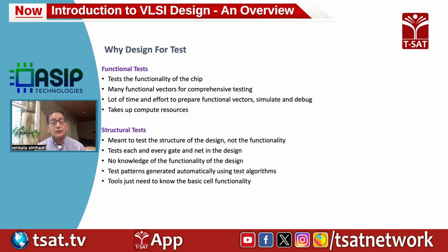There are two ways you can test the chip. One is the functional test. You create some test patterns based on the functionality of the chip, and you observe the outputs to make sure you're getting the expected outputs.